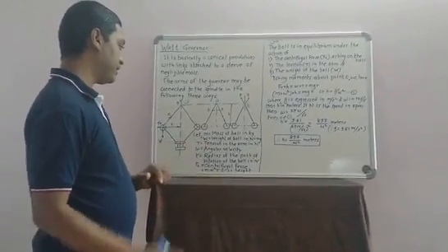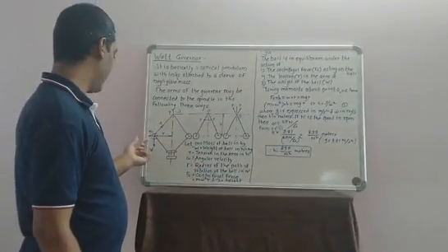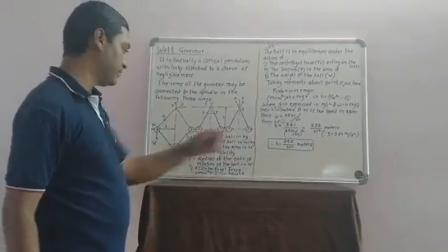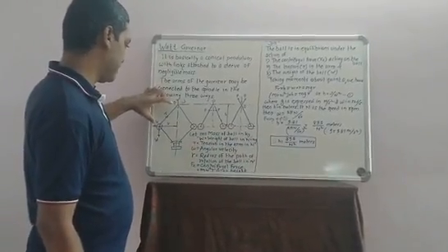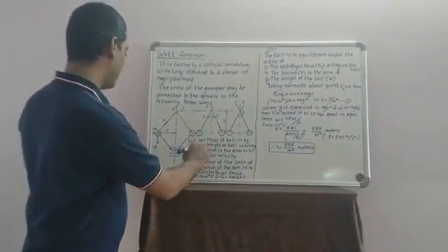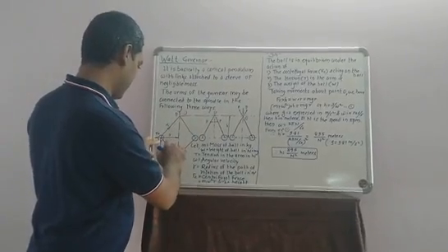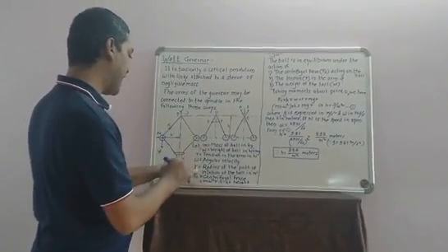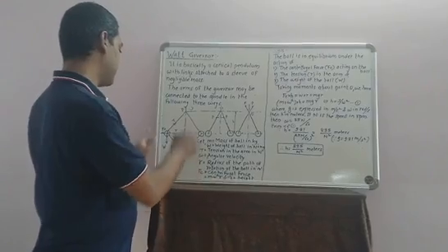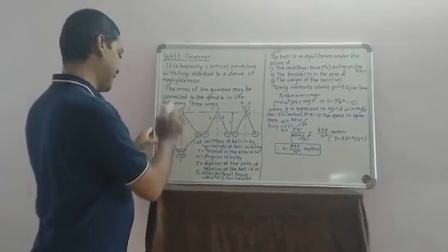Let m indicate the mass of the ball in kilograms, W indicate the weight of the ball in Newtons, so W must equal mg. T indicates the tension in the arm in Newtons, omega indicates the angular velocity of the fly ball and the arm about the spindle axis. Then r is the radius of the path of rotation of the ball in meters. This is the horizontal distance between the center of the fly ball and the spindle axis.